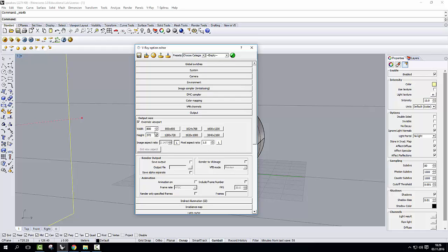If I do this, now I know that the size of my picture will always be the same as what I see in my viewport. Now guys, pay really a lot of attention to this, because everyone is gonna write me an email telling me that the rendering doesn't look like what you see in your computer. This is what you have to do to fix it.